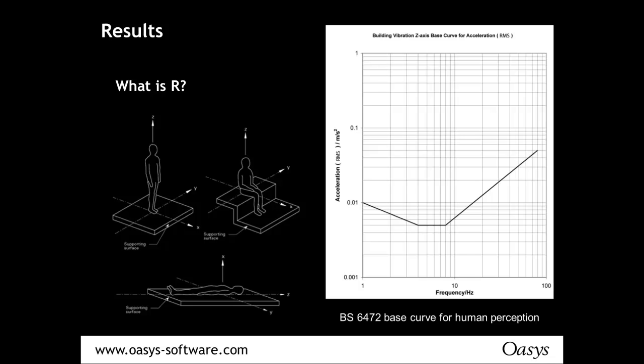If you're walking through a shopping mall or over a footbridge and so on, you tend to be less aware, or maybe less concerned, because footbridges now come in there. With the response value, people are generally happy with a bit of bounce in an exposed footbridge, but are more concerned about bounce or liveliness inside an office building. So the target R value really depends on what the structure has been used for, and so on.